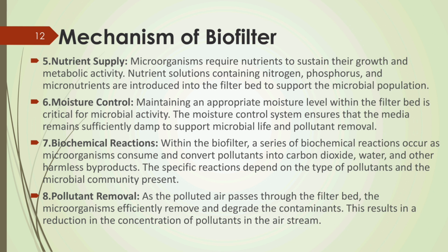Seventh is biological reaction. Within the biofilter, a series of biochemical reactions occur as microorganisms consume and convert pollutants into carbon dioxide, water, and other harmless byproducts. The specific reaction depends on the type of pollutant and the microbial community present. Eighth is pollutant removal. As the polluted air passes through the filter bed, the microorganisms efficiently remove and degrade the contaminants. This results in a reduction in the concentration of pollutants in the air stream.